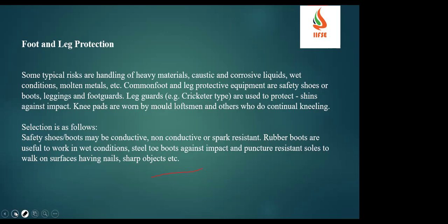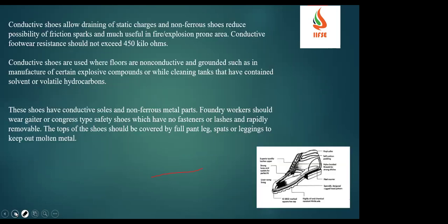There are different kinds of requirements, non-conductive or conductive. So for the mechanical people or maintenance people we give non-conductive shoes, and other people have conductive shoes, and they also have a fiber toe. The maintenance people and other people may have the metal toe, but both will give the same kind of protection. So conductive shoes allow the draining of static charge. We have discussed static charge. So whenever it gets generated, the conductive shoes allow it to go off.